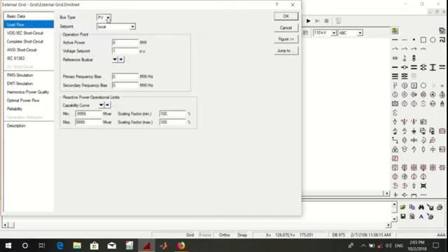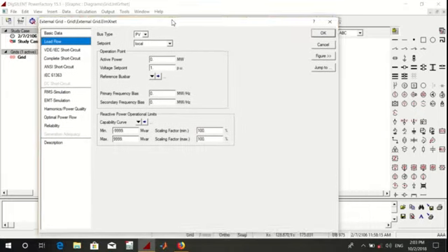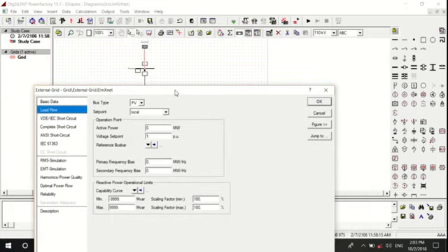Here, go to the load flow. Select the type of the grid. When we feed from the source to any bus bar, according to the load flow analysis theory that we have already learned, here we define one per unit the voltage and the type of the bus bar. This bus is a slack bus. So I select the parameters of the source, that this source is connected to which bus, and the type of the bus. That bus is a slack bus.